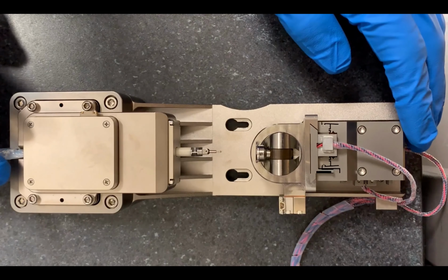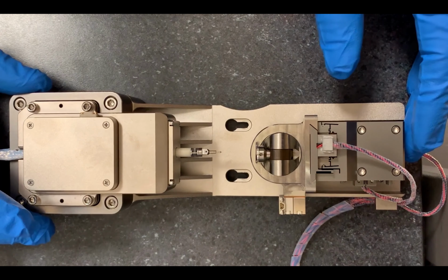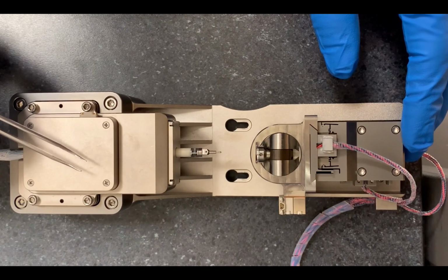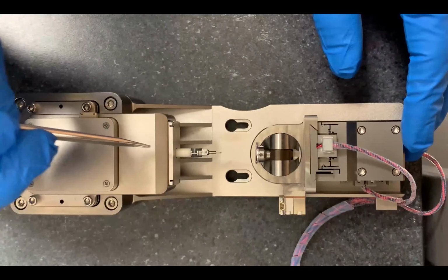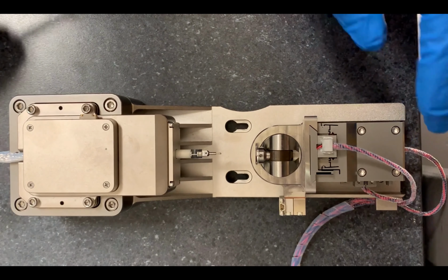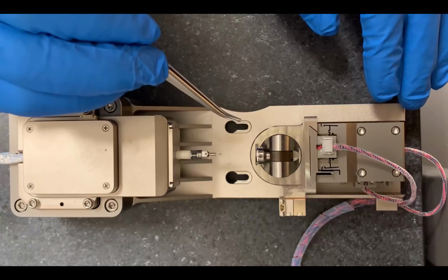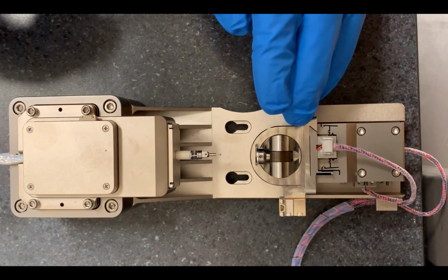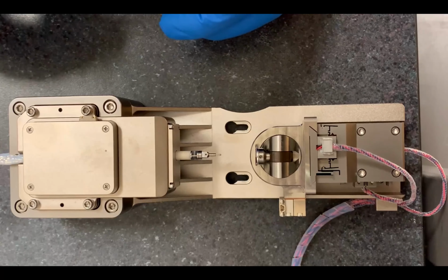Now let me show you different parts of our in situ indentation stage. This is an in situ nano indenter. This is the transducer which controls the loads applied during nano indentation. Here you see a tip holder where we mount different kinds of tips to probe or obtain the mechanical response from the sample. This is the sample holder. We mount our samples here. Right now, a micro lattice is installed on this holder. During testing, the holder part is brought closer to the tip for performing the mechanical test.